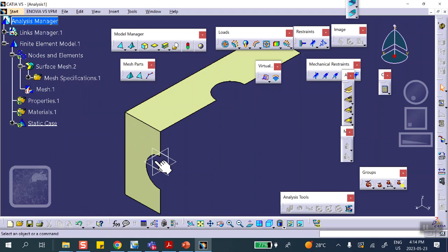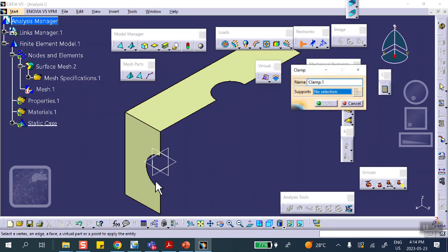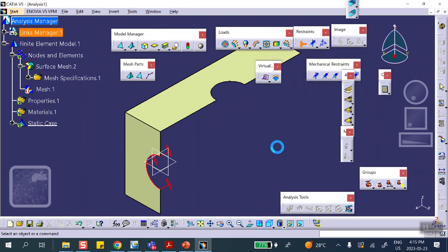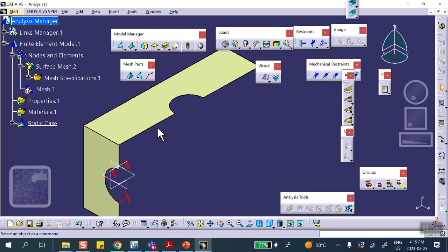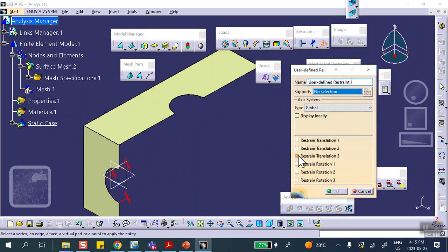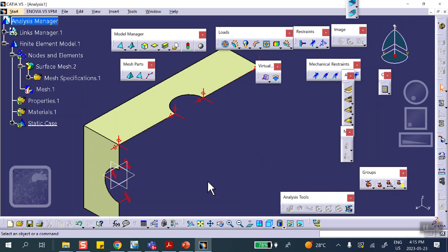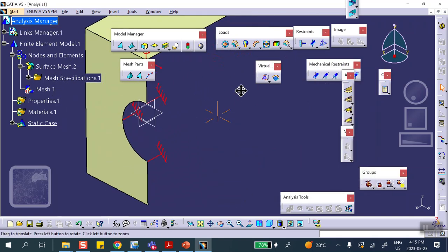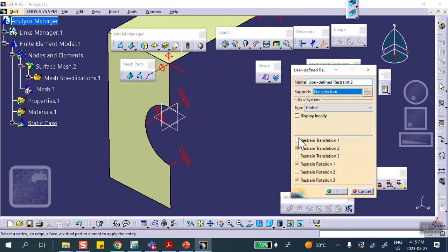As far as this edge is concerned, it is clamped. We are told that this edge is clamped. These are in the planes of symmetry, so user defined: this edge and that edge happen to be in the XZ plane. There is no displacement in Y. Rotation is opposite. Good. And click on user defined again.